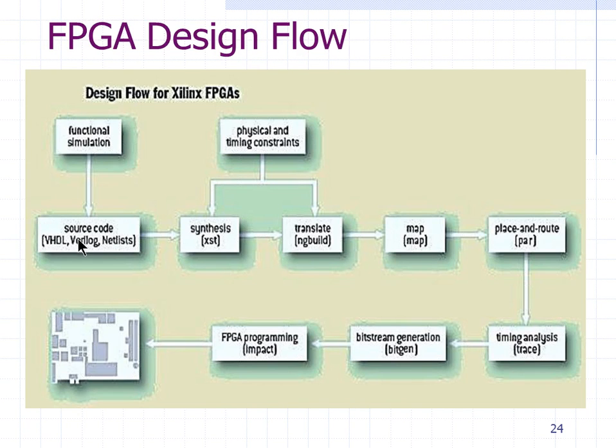Later on, you take the design, only the design, not the test bench, because the testing environment doesn't have to be on the chip. Only the design has to go on the chip. You take the design, which is in Verilog, and you follow this back-end process. The back-end process consists of synthesis, mapping, placement, and routing the design, something called static timing analysis, and finally something called bit file generation.